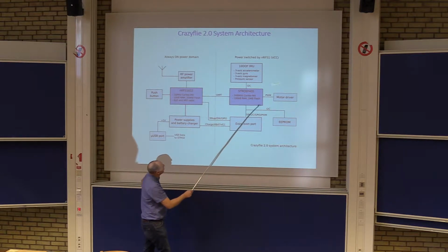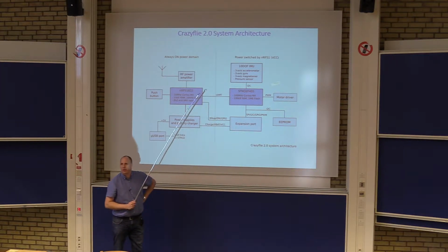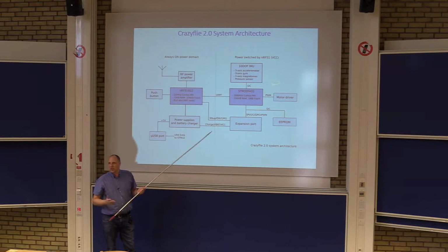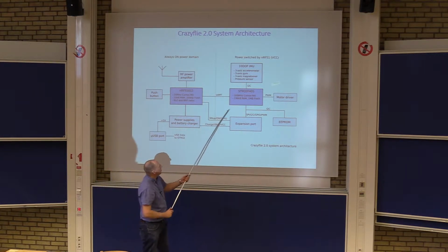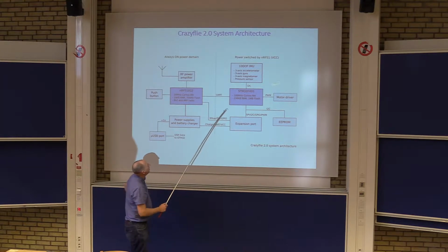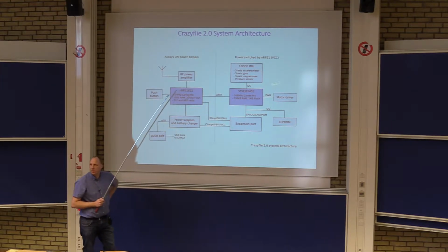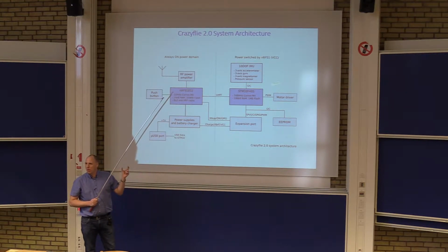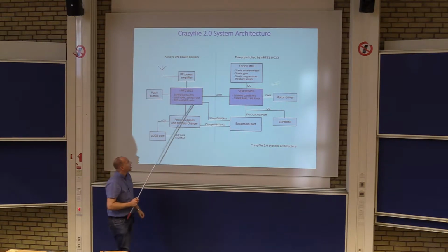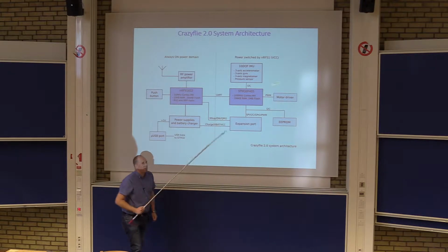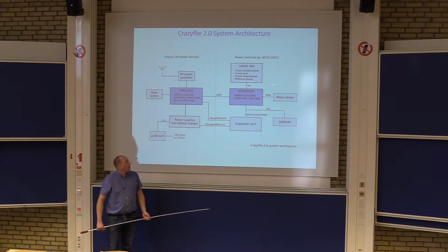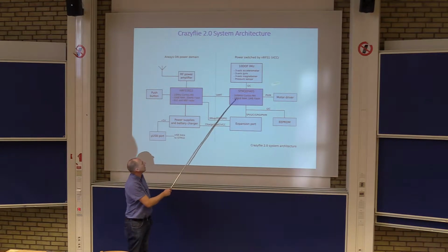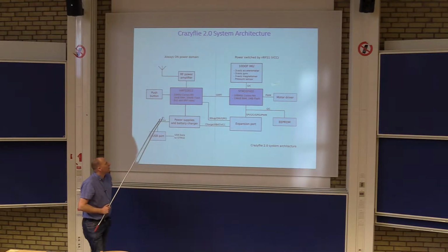This is where your control algorithms and your sensor signal processing algorithms will execute. This one is a 32-bit processor, meaning that every integer is represented using 32 bits, basically 32 binary variables that can be true or false. It's running at 168 megahertz, and it has close to 200 kilobytes of RAM and 1 megabyte of flash.